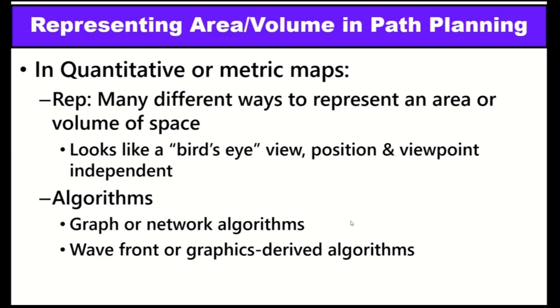The reason is very simple. Sometimes areas are very large and the metric measurements are not so accurate. Many times GPS accuracy is also a problem. Many times there are sensor limitations and range problems. So for a large area, I cannot always establish metric maps correctly. So I have to rely on topological path planning, or I can go the hybrid way.